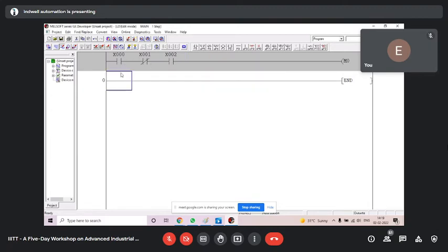Now you see, you want parallel. In Mitsubishi, don't click here. If you click here and you take parallel, you see M0, enter. It is saying the edit position is incorrect. It means you have selected the wrong position. You come down to the next ladder. Automatically it came. So you come to the next ladder, click here, and then you take parallel, M0.